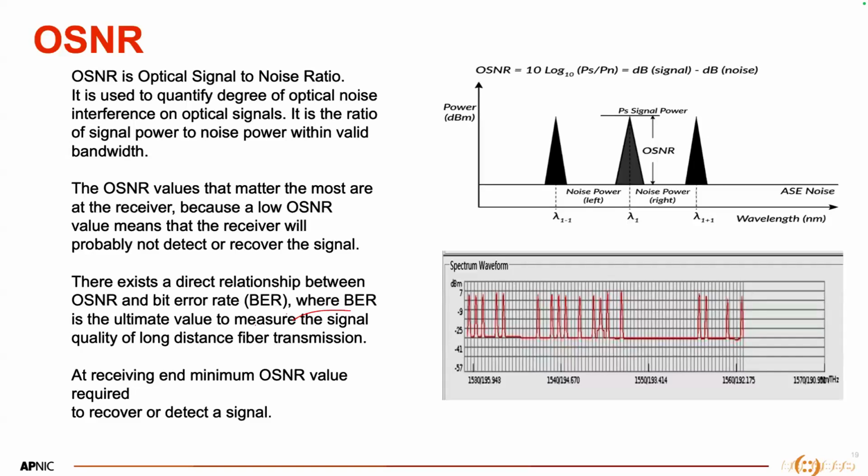First, we use pre-amplification and then we use a booster. Pre-amplification works when the signal arrives in the station, and the booster works when we are going to send the signal towards the next station. So we are boosting the signal before sending it into the field, and we are amplifying the signal before receiving it in the next node. I hope that clears your query.